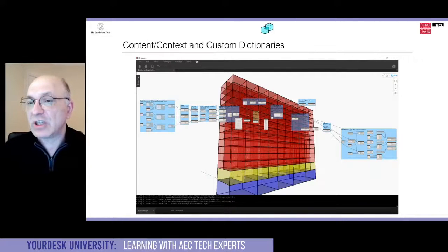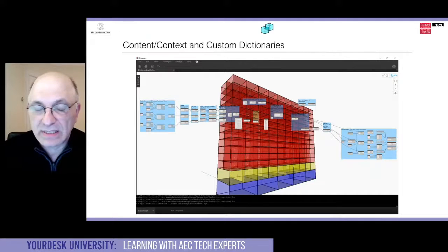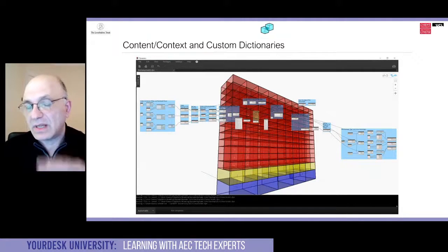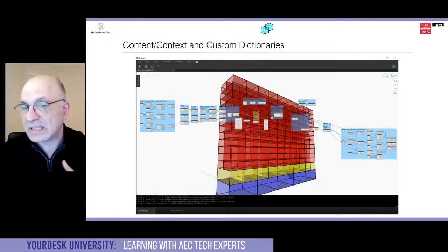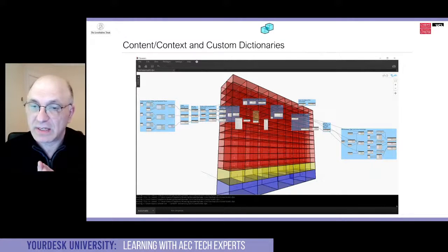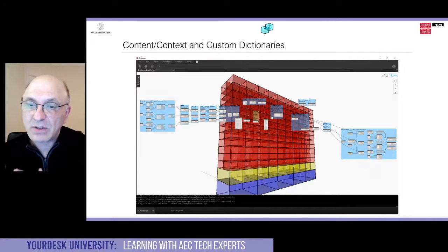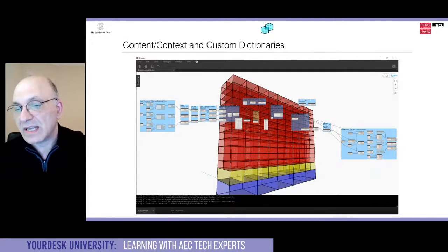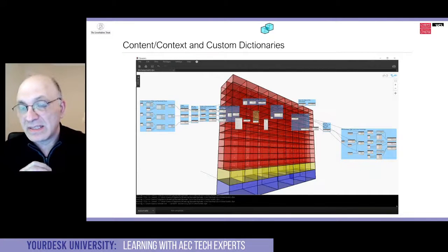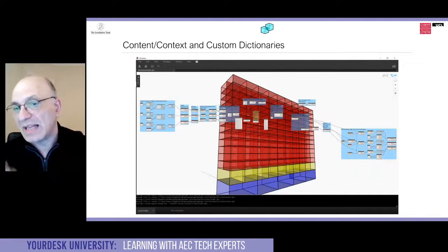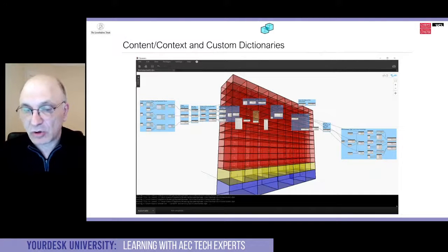As I said, cells can have dictionaries. Let's say I have retail, I have offices in yellow, and then I have residential units on top. So I have 3 cells stacked on top of each other before they are subdivided, right? So you can put 3 dictionaries in each cell. Now, when you slice your building using Topologic's slice mechanism, the new cells that have been sliced, now I've generated tens of new cells, they know their parent cell, meaning that the dictionary survives the Boolean operation and ends up being placed or copied into all the children cells that were created.